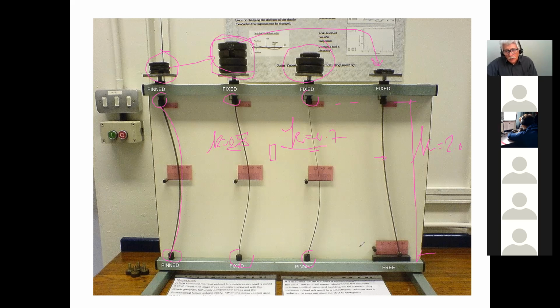So that's what I like about this: just keeping everything the same, the length of your compression member, the same cross-sectional area, the same material and everything else, the end conditions alone will affect the resistance of a member in compression. When I saw this the first time, it was very clear to me what they're trying to show you. They fixed this, they pinned that, and here it was fixed there and free to translate; all they did is put it on a roller, so it was free to translate in a plane.